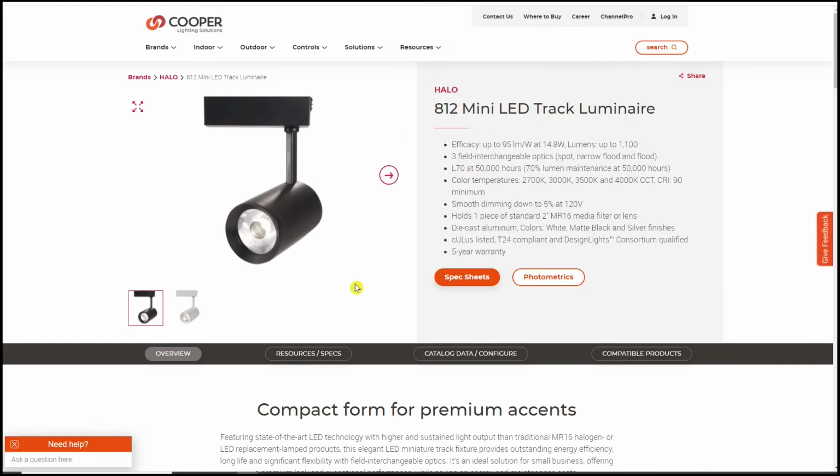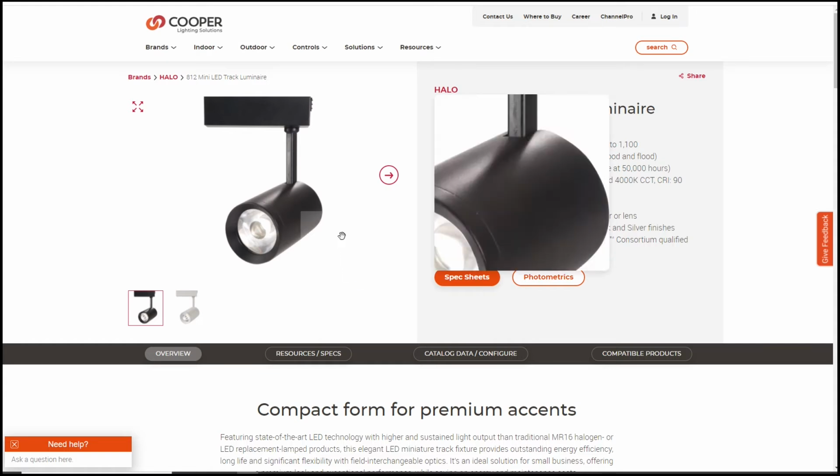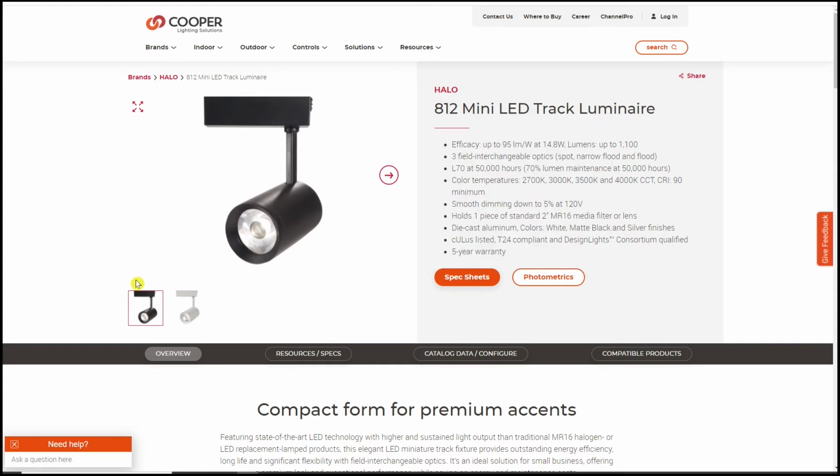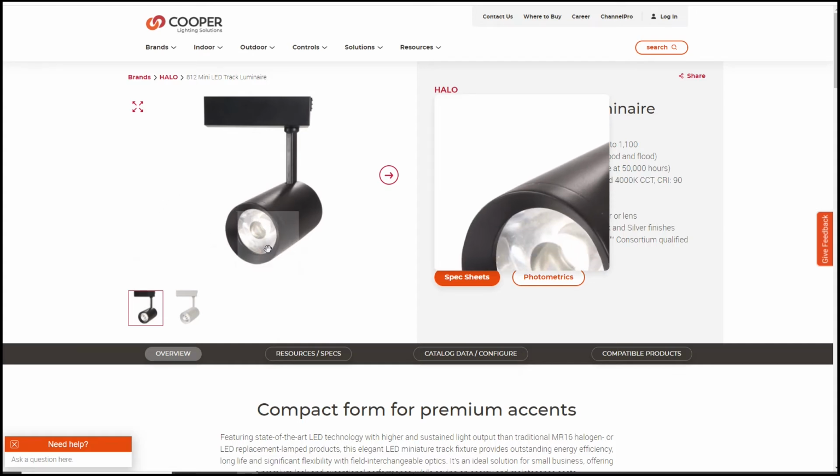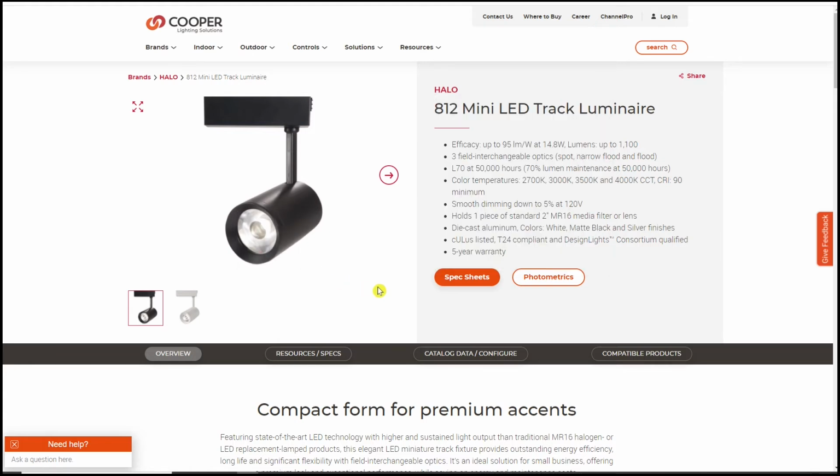Two that I was considering, two types of lighting fixtures. One was track lighting, which is basically a linear track. These are heads that can be moved along that track, and the tracks themselves come in lengths of 2, 4, 6, 8 feet. So they're very flexible, highly customizable. And this type of fixture is an LED fixture, so it's pretty small in terms of 14.8 watts, which is the power it uses. Lumens, that's actually the lighting intensity at the fixture, is up to 1100 lumens.